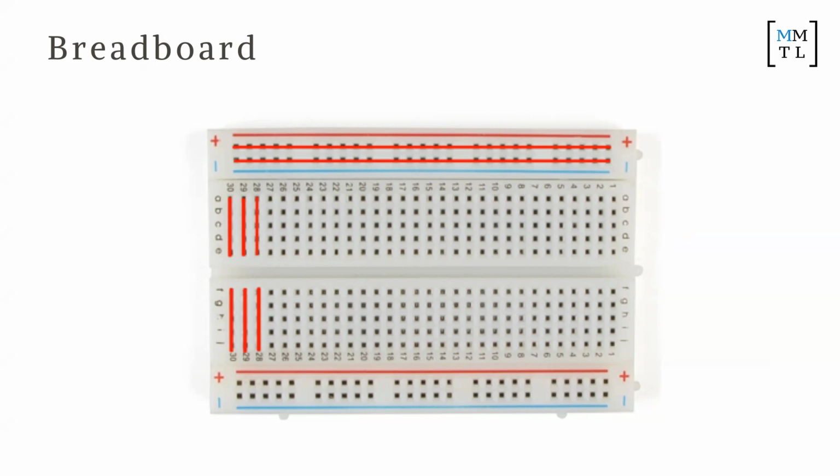Okay, and what the plus and minus usually mean is that the plus is 5 volts or high, right? And then the negative is usually ground. Okay, so please don't screw that up, because when we're trying to debug your circuits, if you flip 5 volts and 0 volts, it's going to lead to really nasty behavior. We're not quite sure what's happening, right? And so you do want to make sure that 5 volts is always attached to this plus and 0 volts is always attached to this.